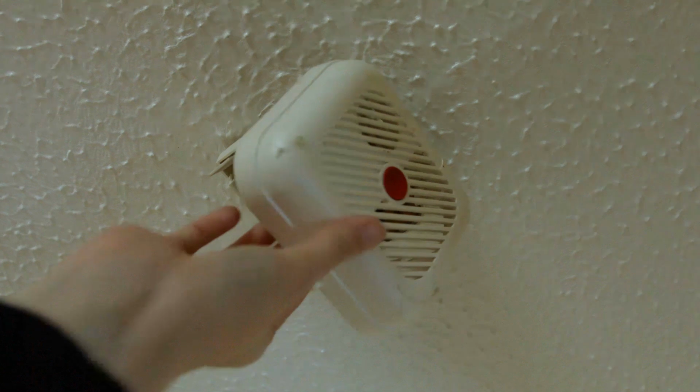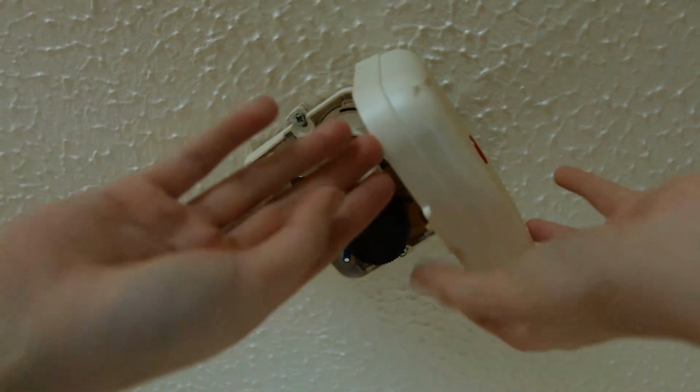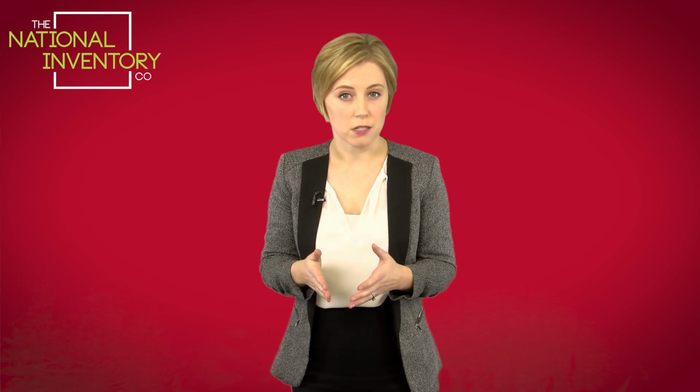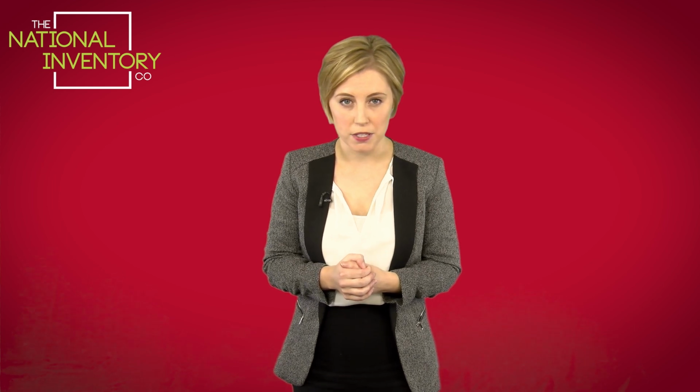Please be aware during your midterm inspections that tenants often remove a battery as the fire alarm keeps going off. In such a case, it's important you record at your midterm inspection that the battery has been removed as a direct result of the tenants. Also record that you have written to them to inform them that this is a legal requirement to have a working smoke alarm and that a battery will need to be put back within 24 hours.